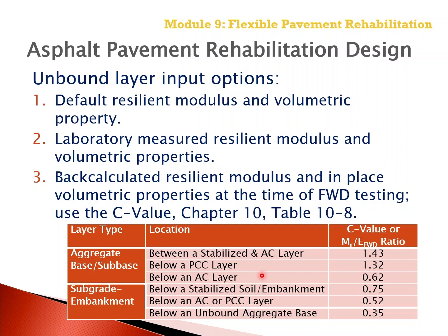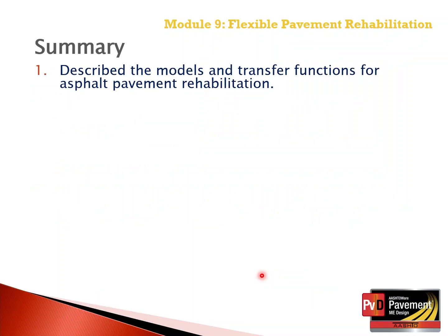So the resilient modulus entered into the software for new design as well as rehabilitation design needs to represent the volumetric properties at which the resilient modulus was established, either through laboratory testing or back calculation of elastic layer moduli values.